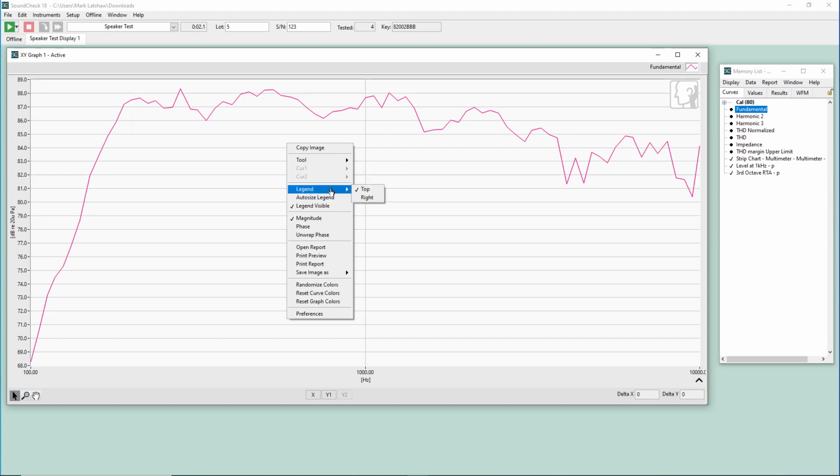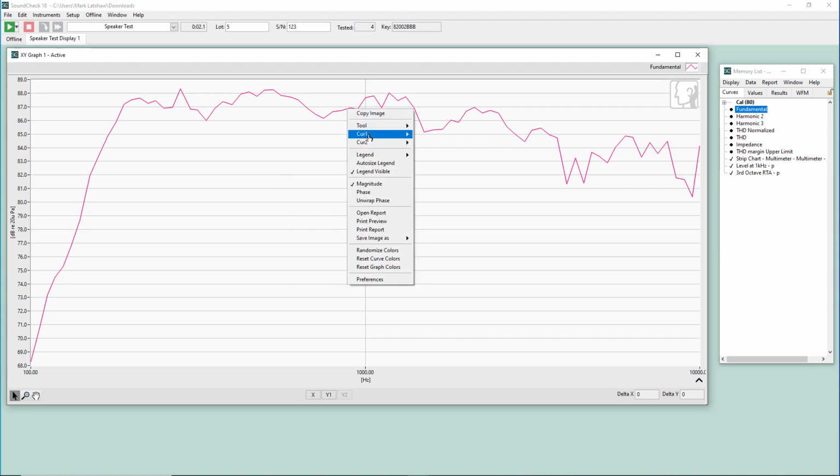Cursors 1 and 2 can be added, but you must be right-clicking on a curve or a waveform. If I right-click on a curve, then I can either place it in the location that I clicked by dropping it here, or snap it to the maximum or minimum point. Once placed, it will show the name of the curve it is currently on, along with the X and the Y points. By clicking on the cursor, it can be dragged to different areas.